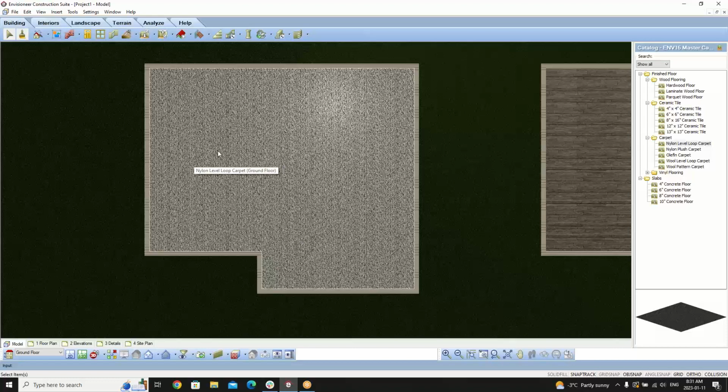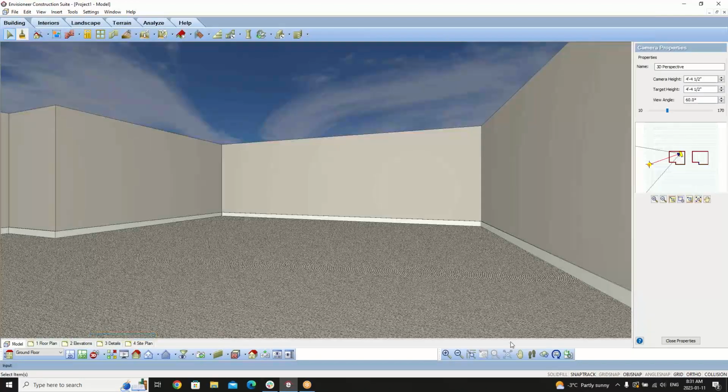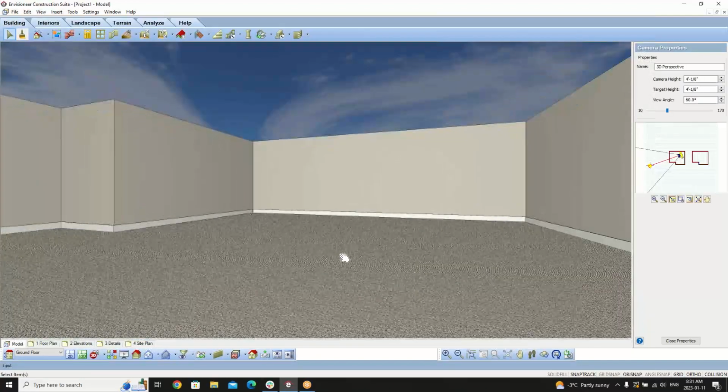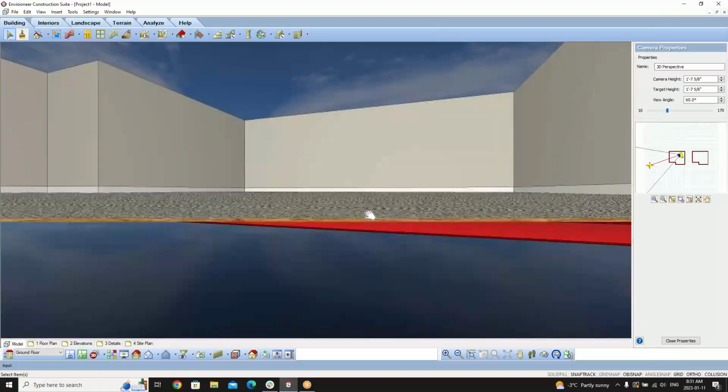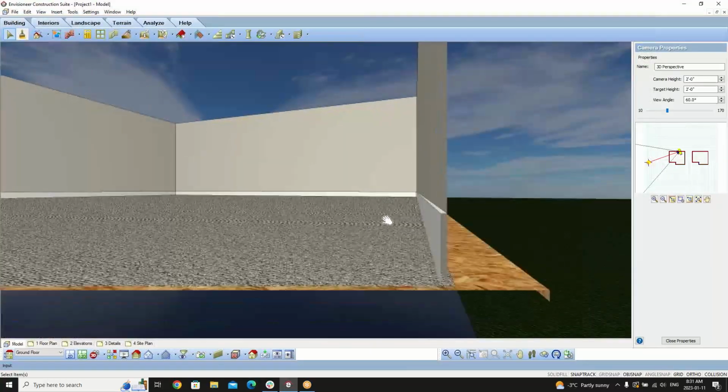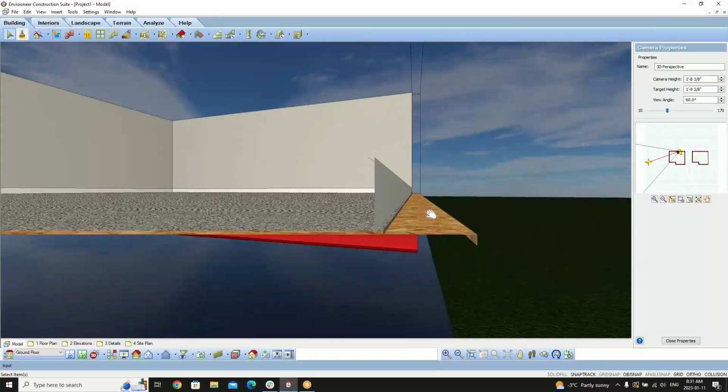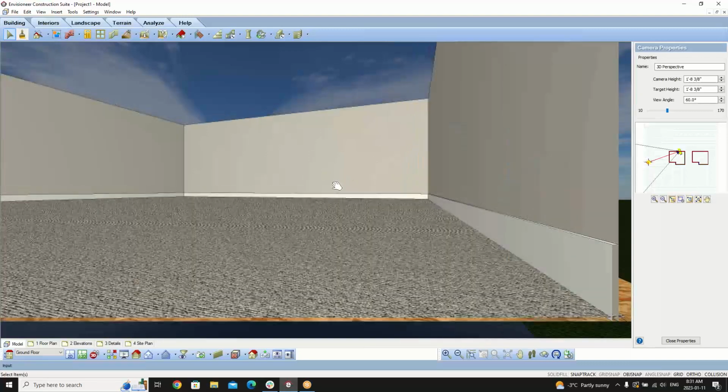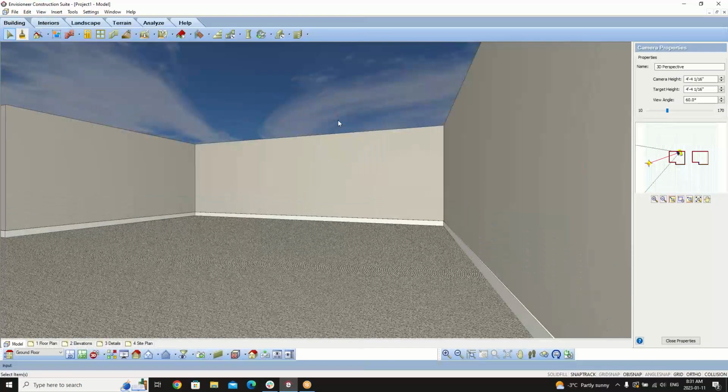And in that 2D plan view now, or designer's plan view, I can see that carpet. If I go into a 3D view, I can see that the carpet is now sitting on top of my subfloor, but it also terminates at the edge of the wall where my sheathing would go all the way to the exterior edge. So that's how you can add in your floor surfaces.